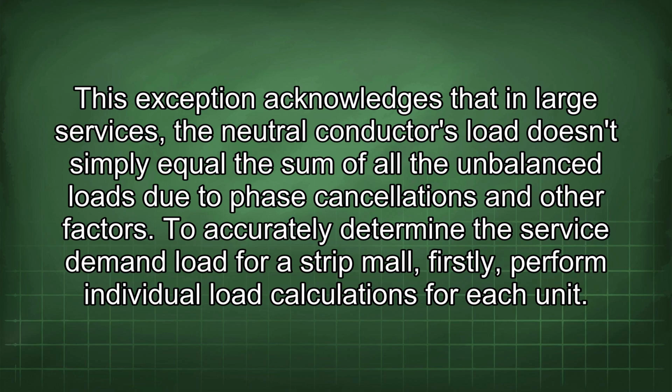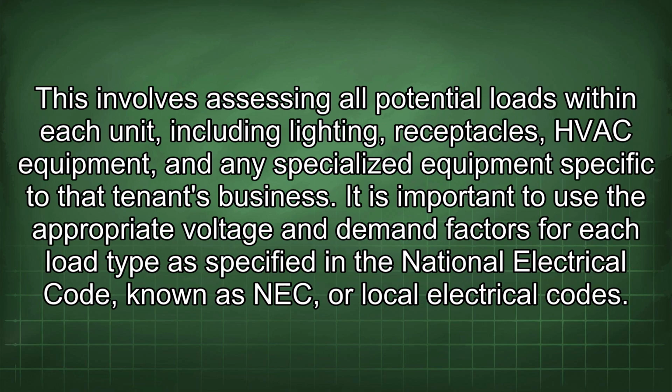To accurately determine the service demand load for a strip mall, firstly, perform individual load calculations for each unit. This involves assessing all potential loads within each unit, including lighting, receptacles, HVAC equipment, and any specialized equipment specific to that tenant's business. It is important to use the appropriate voltage and demand factors for each load type as specified in the National Electrical Code, known as NEC, or local electrical codes.